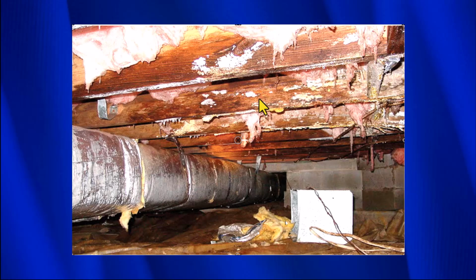I don't know how much time most of you have spent underneath houses, but what you see right here in the crawl space is not unusual. I just want to point out some of the things that you see here. So right here, this is some insulation that's fallen down, and the insulation is a problem because if you don't have a respirator, you'll end up breathing in some of this insulation fiber, and it's very, very unhealthy. It can get into your eyes and get into your lungs. So you must always wear safety equipment when you're in a crawl space like this.